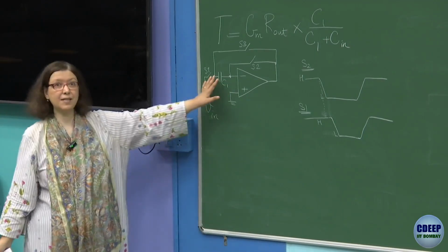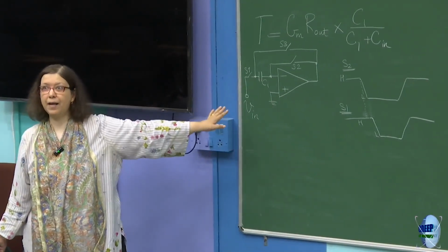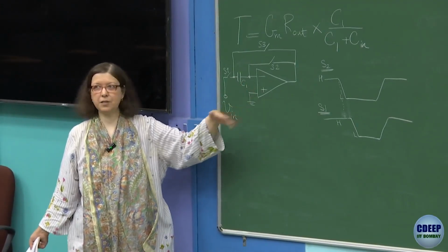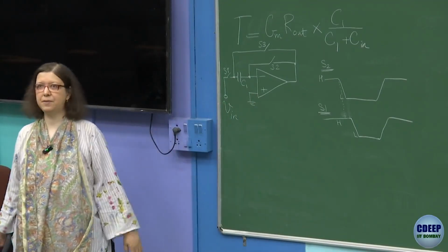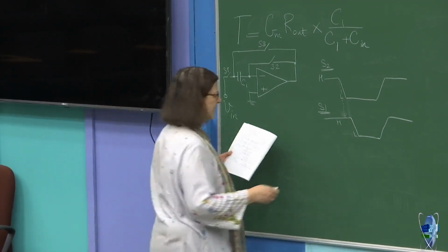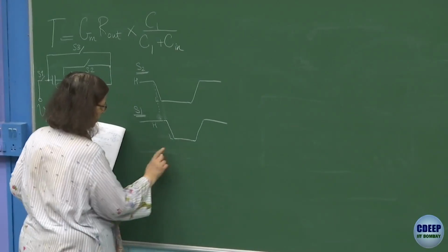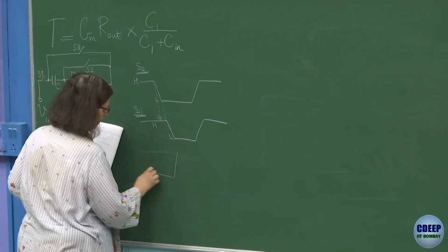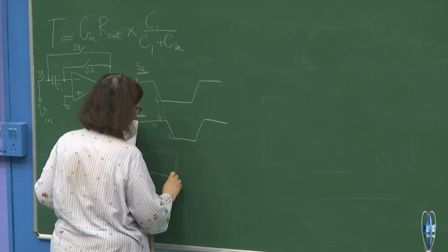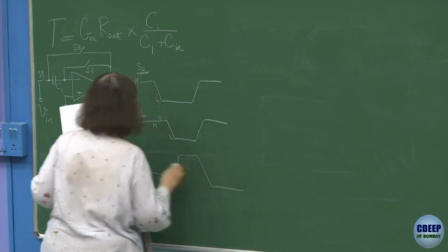We have discussed that situation, if you remember, in the bottom plate switching case, and we showed that in the last lectures. With bottom plate switching, the effect of charge injection completely goes away, even if it happens due to S1 here. And finally, S3. S3 and S1 are more or less similar, almost simultaneous. Maybe a little difference, but not much. So this is for S3.